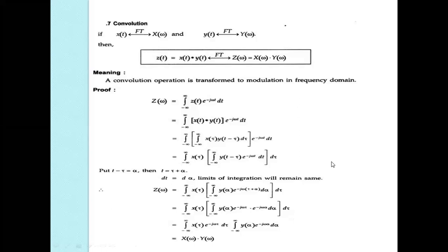So convolution. The next, eighth property is the integration property. The integration property is not there in the Fourier series; we have it only in the Fourier transformation. So what is the meaning of the integration? Integration in time represents smoothing in the time domain. This smoothing in the time domain corresponds to de-emphasizing the high frequency components of the signal.